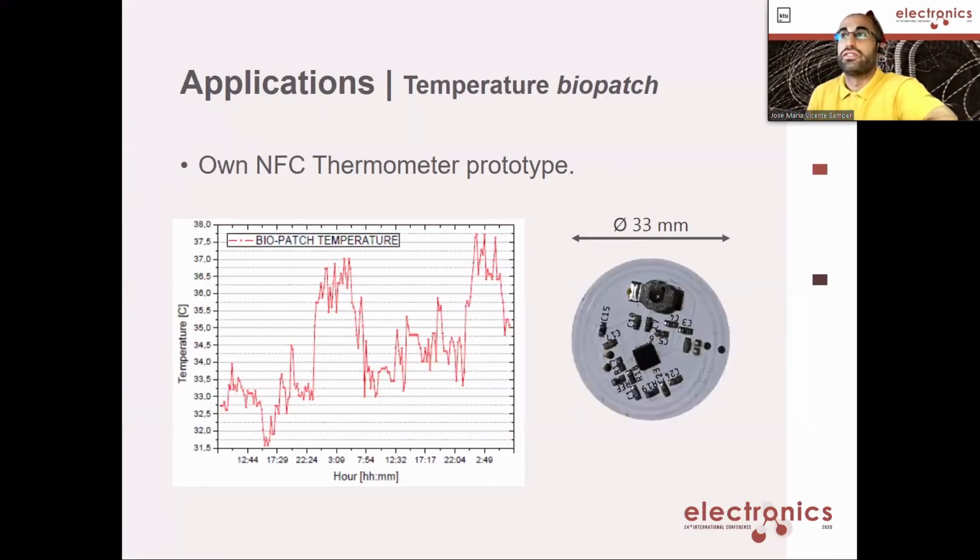In the application section, we can see 2 applications with the NFC to BLE bridge. The first one is a temperature biopatch developed in our laboratory. It's a small NFC device that measures the body temperature of the user every programmable period with an autonomy of more than 1 month. We can use the system in flash mode during the day and convert it into continuous mode with the bridge at night to go to sleep, for example.